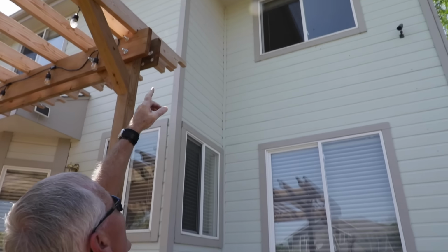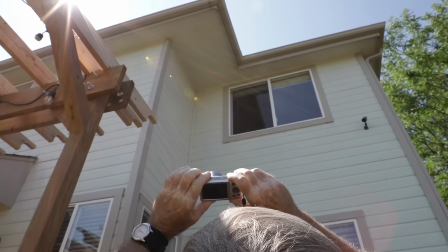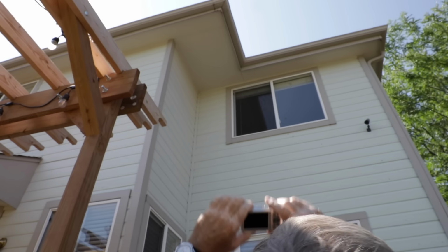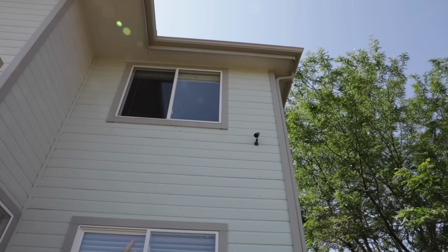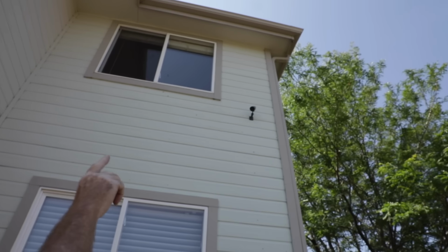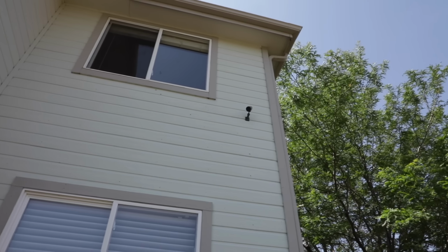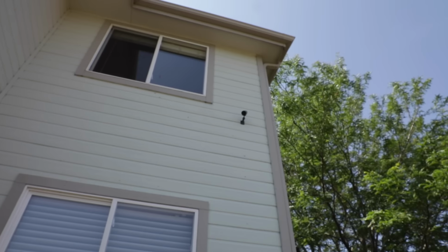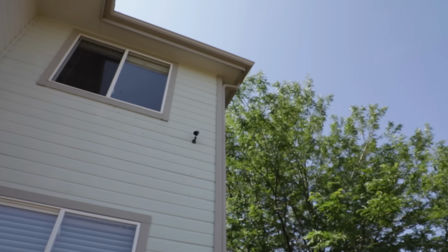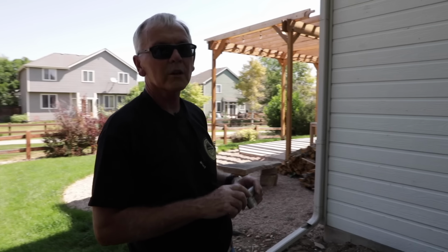And I can see a little water damage right up here on the corner on the fascia. I'm going to take a photo of that, focus in, and it looks like we may have some on this outer corner here as well. Try and capture that. That concludes our soffit, eaves, and fascia inspection. We did find a few minor items. We'll note that in our report, and we'll move on to the next section.